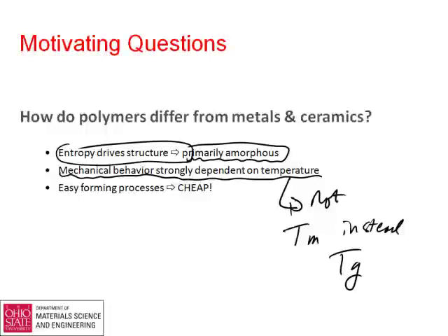I'll bring this up again at the end, but one way you can see TG is if you look closely at how an ice cube forms: you have a very clear difference between solid and liquid. Candle wax is different. There isn't a real clear boundary of solid and liquid. Some is harder than others, and there's a temperature range over which properties change pretty quickly, but it's a continuous change in properties.